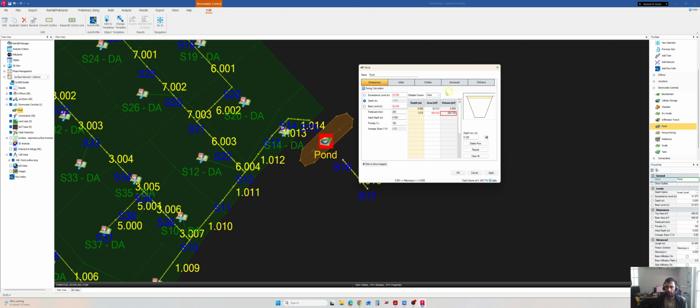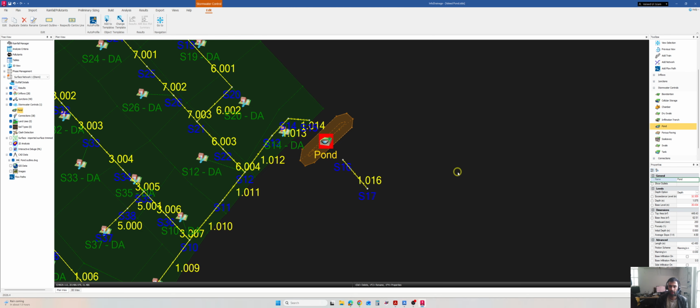As you can see, I have the pond design as per the sizing calculator, but there are other things that we can also see. You can see this is the bottom line of the pond, and then this is the top of the bank. Now we will see how we can calculate our discharge, our runoff coefficients and percentage impervious values. That will also help us in our calculations. So for the PIMP values, we will just go to the tables. You can see the tables.